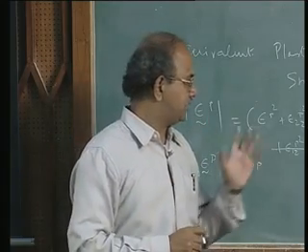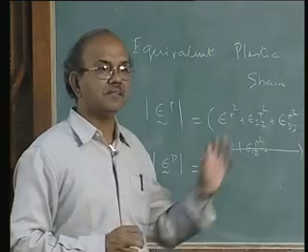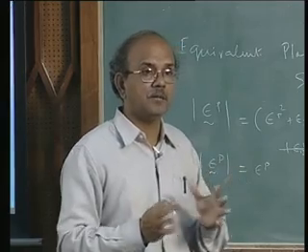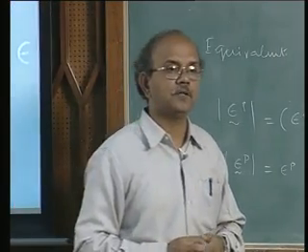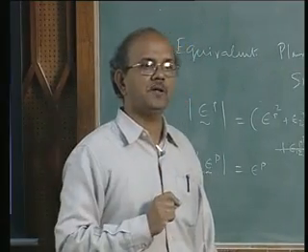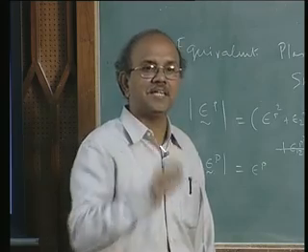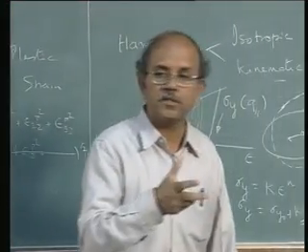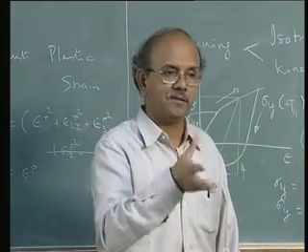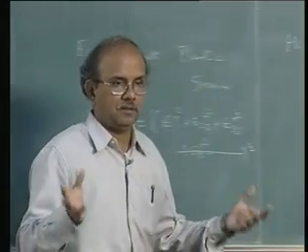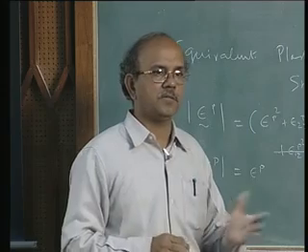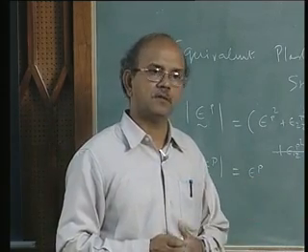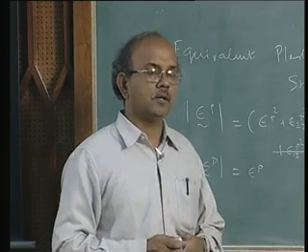So, just a word of warning: the materials we are looking at, as elastoplastic, are nearly incompressible. Why is it nearly incompressible? Because in the elastic regime, or elastic strains, I still have my Poisson's ratio to be 0.3. Not that every material has 0.3, but typically 0.3 for steel. It can be 0.2 or so on.